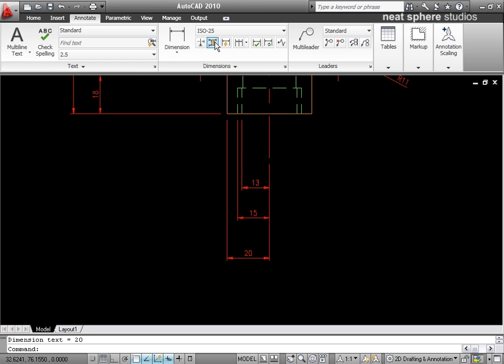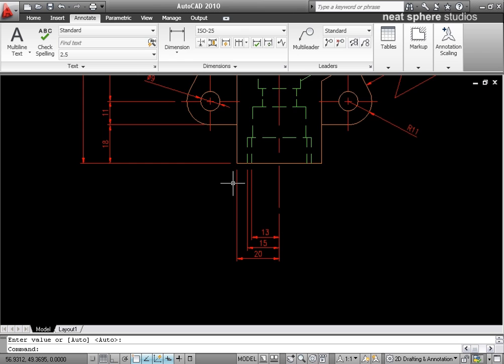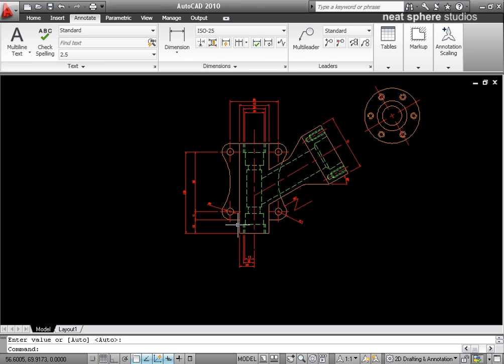And of course, if I want these to be stacked correctly, so I've got auto spacing, I'll go back to my annotate, I'll go to my adjust space, and I'll select these three objects. I'll press enter and then enter again, and you can see all of these baseline dimensions have now been auto spaced, as well as being placed correctly within our drawing.